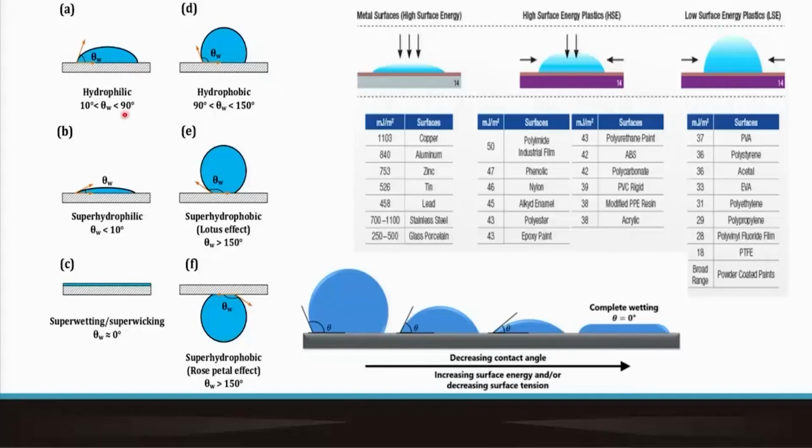But on the other hand, this is one extreme, and in the limit the so-called wetting angle that is subtended, or the theta that we were talking about, could be as small as just a few degrees, even less than 10 degrees. And if it is truly super wetting or super wicking type, which means it will have zero wetting angle, you won't see a hillock forming at all, and hence the wetting angle will be close to zero.